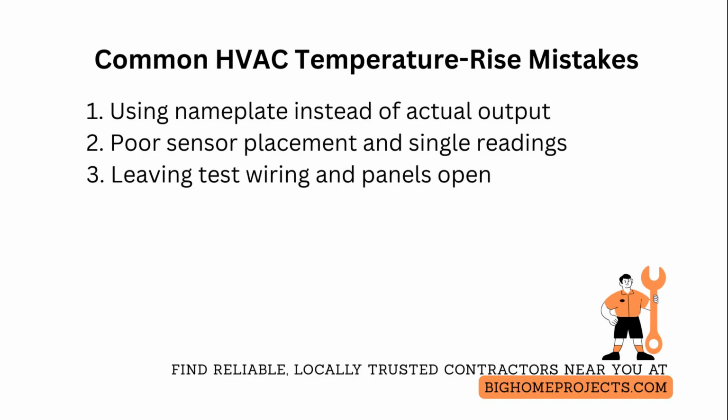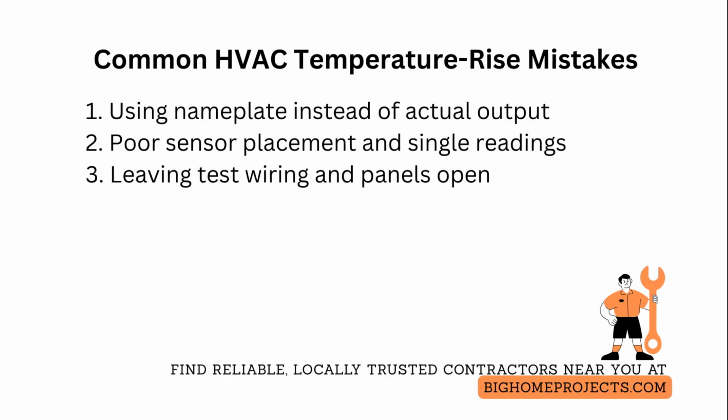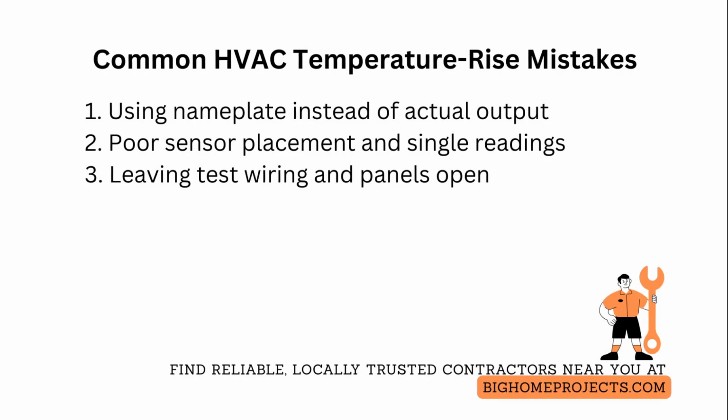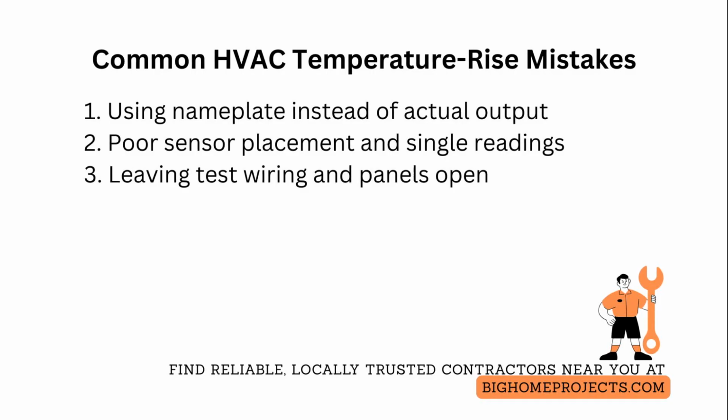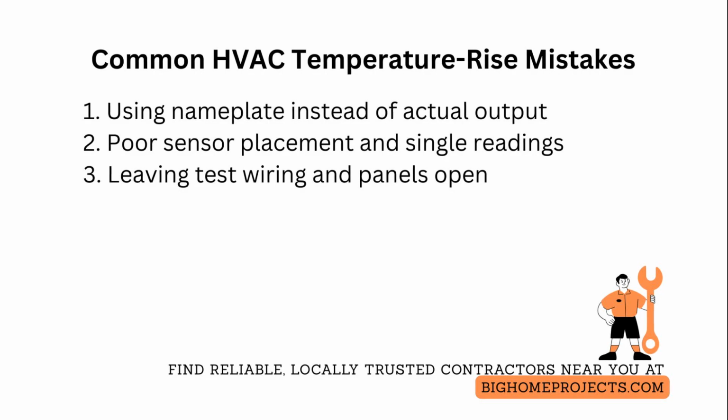One of the next frequent issues is poor sensor placement and single-point readings that create noisy data and incorrect temperature rise. Fix this by averaging multiple readings at standard distances from grills, securing probes to avoid airflow disturbance, and logging for a stable interval.